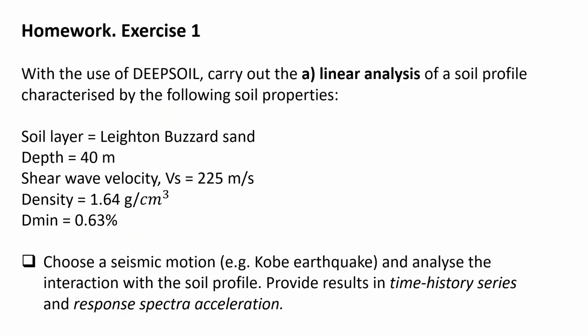I want to finish this presentation by saying that I'm going to add a couple of exercises for you to complete with DEEPSOIL as part of your own homework, and that would be the practice for the summative assessment, because I will ask you to undertake linear analysis and equivalent linear analysis of a homogeneous layer and of soil profiles with maybe two and three layers, to see how the soil behavior changes and what is the amplification of the signal in terms of acceleration, velocity and displacement on top as a consequence of that interaction between seismic waves and the soil profile.